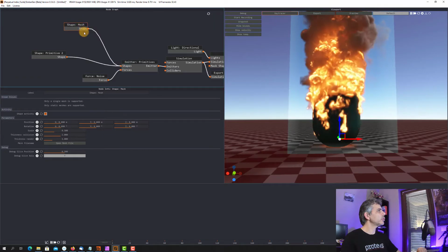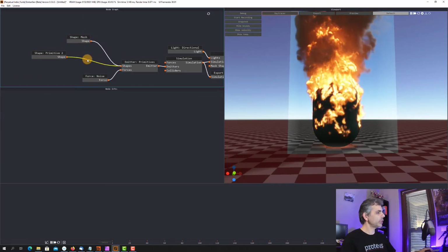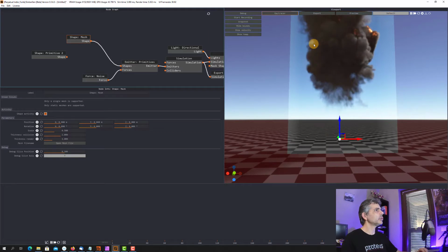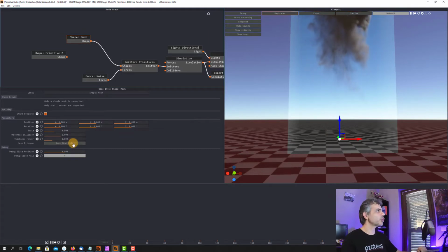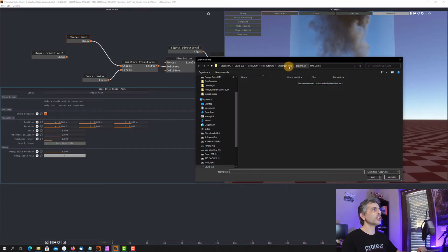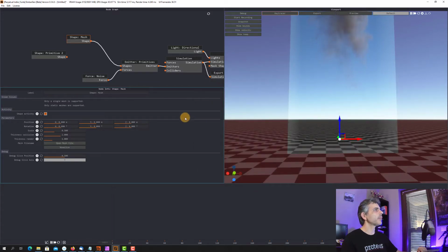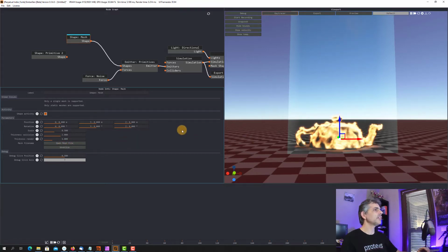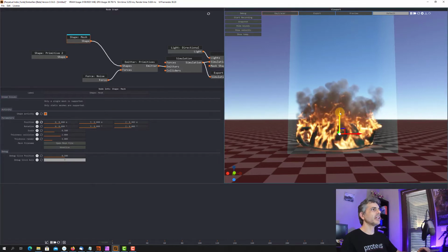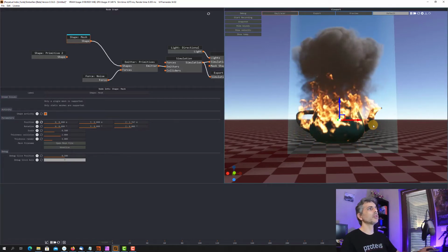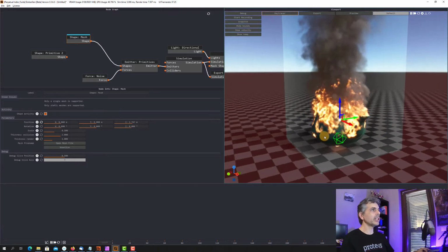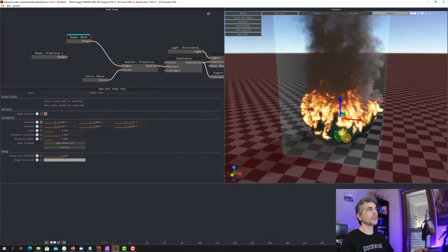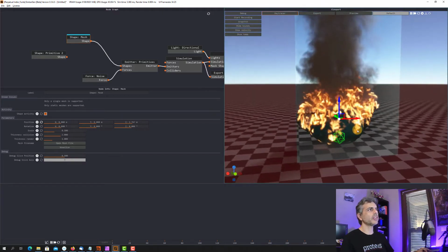So connect the mesh shape to the emitter. Then we get to remove this one. You see that we have no more simulation, and that's obviously clear. We have to load the mesh we created, but again, we have no emission. And that's because the mesh is essentially a polygon mesh. We need to voxelize because it needs to be generated inside the voxel space, okay? It is an internal conversion. Now it is visible, and it is working as the previous primitives we had before.